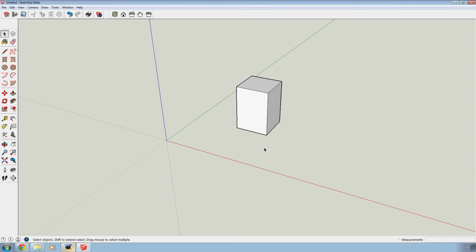Well, if you don't get what you want, then just click somewhere else and then the items you've selected will be deselected. Single surface will show its selection as a load of dots on the surface. If I'd clicked twice I would have just got the single surface that I started on plus the lines around the edge. Clicking 3 times will get me the whole thing. All the connected geometry will be selected.